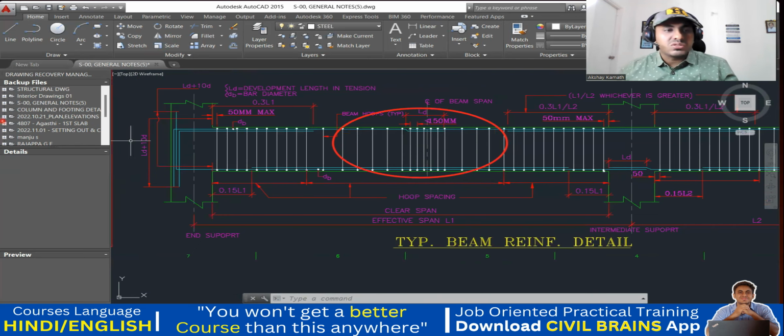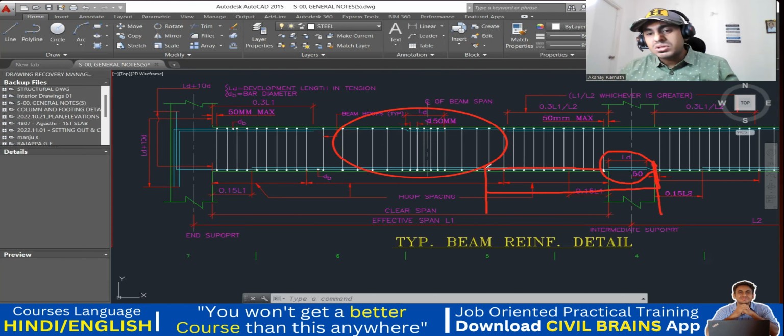Within L by 4 you can do. See, actually, if it is not an earthquake resistant structure, then you can lap within L by 4. Up to here you have a chance. From here you have a chance. You can lap anywhere. But here, usually they have lapped it from an earthquake point of view. You can even lap up to this distance. Beyond this, you should not go. So as far as possible, try to do it within this much junction only.